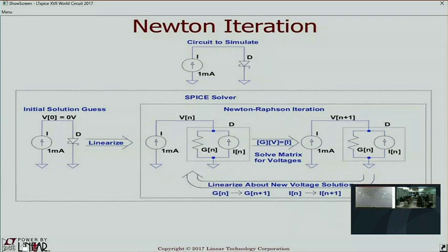Now it might not be obvious what the IV curve of a transistor is. Well, let me say what's here first. If you just have this, you have I of 0, this IV line, here you have I0 plus this delta V times dI/dV. This is a conductivity, and that's a current. So this is actually a Norton equivalent circuit. That's what that is. Okay. The first two terms of a Taylor series comprise a Norton equivalent circuit, and you replace all the nonlinear elements in your whole schematic with Norton equivalent circuits.